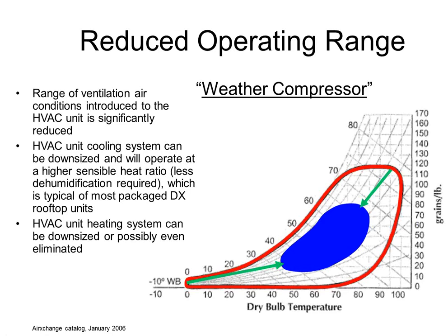In terms of my rooftop sizing, I'm much more appropriately sized to be able to handle that blue scenario because I don't have to deal with the big range. The ERV is trimming everything for me. It's humidifying, dehumidifying, heating, and cooling, so I don't have as much to deal with on the rooftop, which means the rooftop doesn't have to be oversized, it doesn't have to short cycle, all that great kind of stuff.